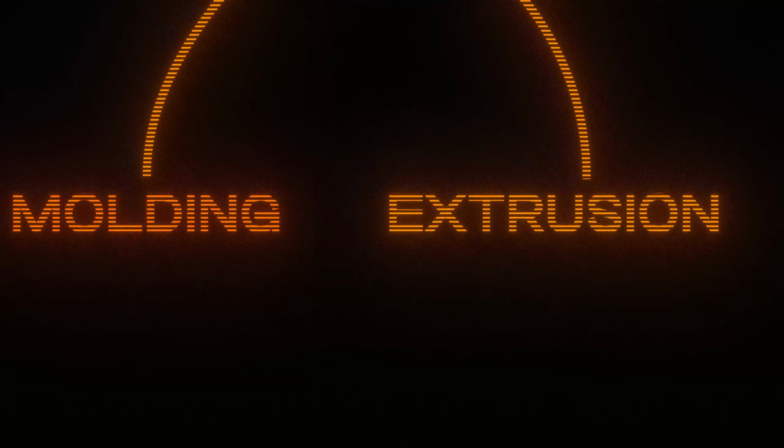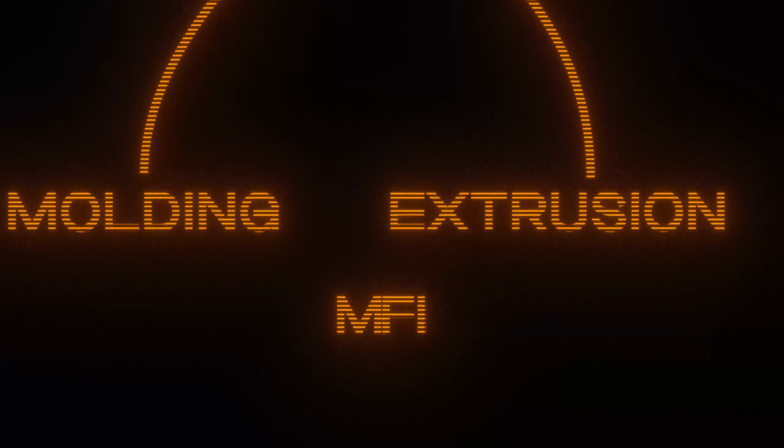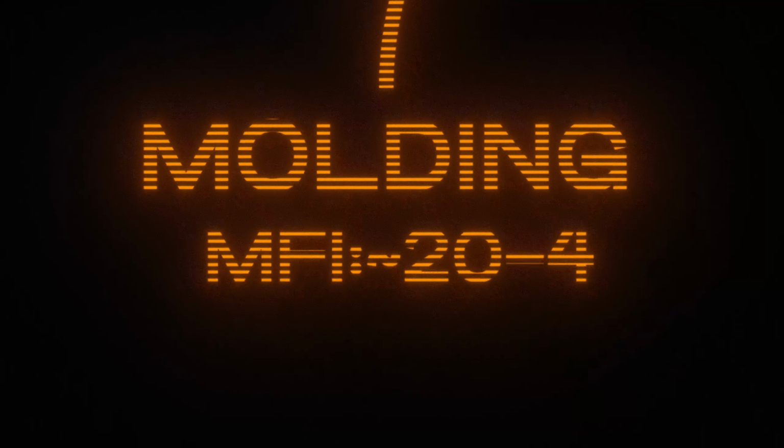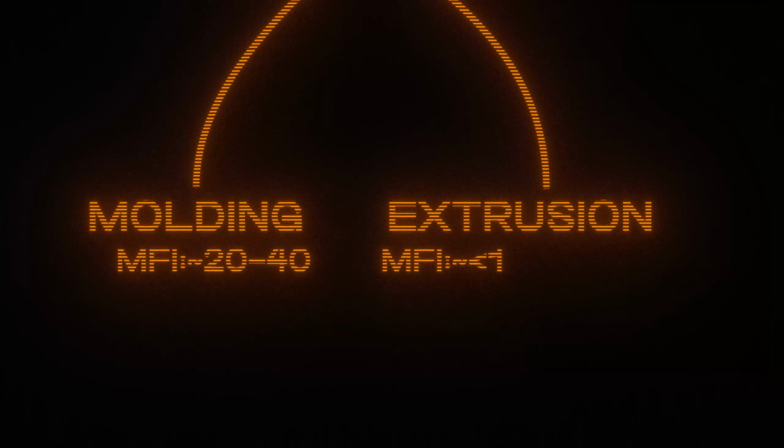After polymerization, the resulting polypropylene is presented in the form of granules that can be used in 2 different ways: injection molding and extrusion. The main difference between these 2 methods is the melt flow index, MFI. The higher the MFI of a thermoplastic, the lower its viscosity. Extruded polypropylene has a low MFR, usually up to 1 gram per 10 minutes. This is necessary for the material to retain its shape during the drawing and forming of products. Injection molded polypropylene has a high MFR, usually 10 to 50 grams per 10 minutes, which allows it to easily fill molds during injection molding.